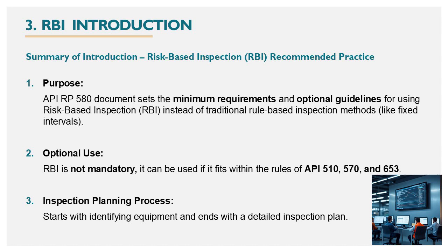Agenda number 3 is risk-based inspection or RBI introduction. Here, we'll define what RBI is and explain how it differs from traditional inspection approaches. RBI focuses on prioritizing inspection efforts based on risk, rather than fixed intervals. Summary of introduction of risk-based inspection or RBI recommended practice.